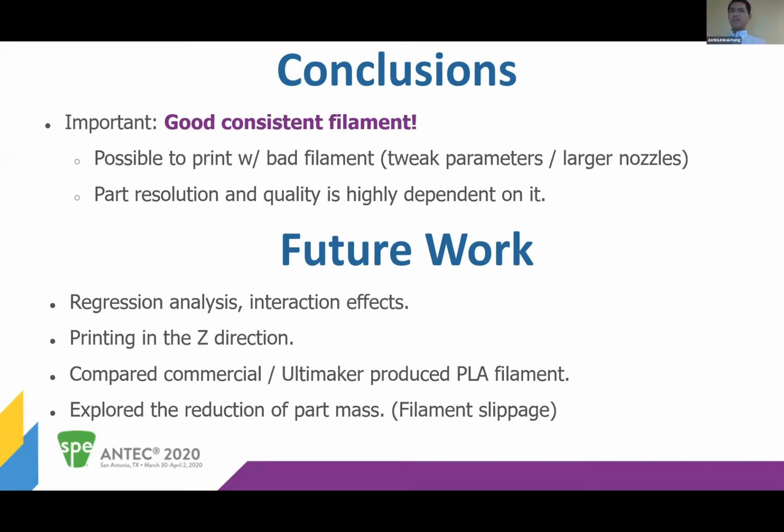And basically, in some sense, if you also print with smaller nozzles, it can affect your part resolution. So some future work that we might have done, we could have done more regression analysis and studied the different interaction effects. We also printed only in the X-Y direction. I know there's a lot of interest once you print in the Z direction.